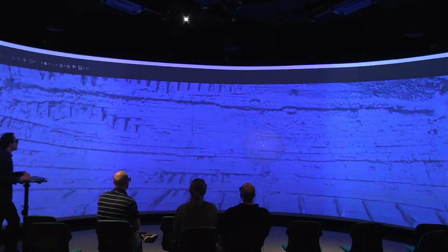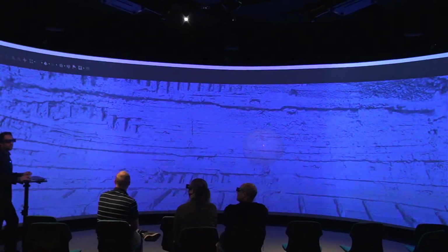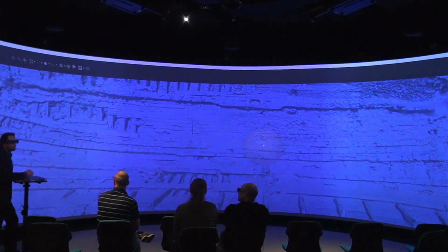The way I see it, I max out the key points when I do the feature extraction. Usually I use 5 million key points and take the tie point limit off and set it to 0. Even if there's noise in the sparse reconstruction, you can manually edit that out.